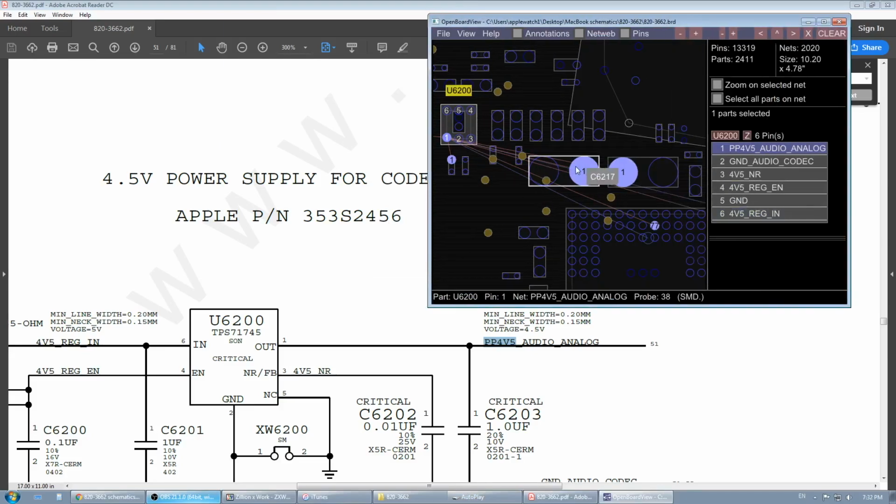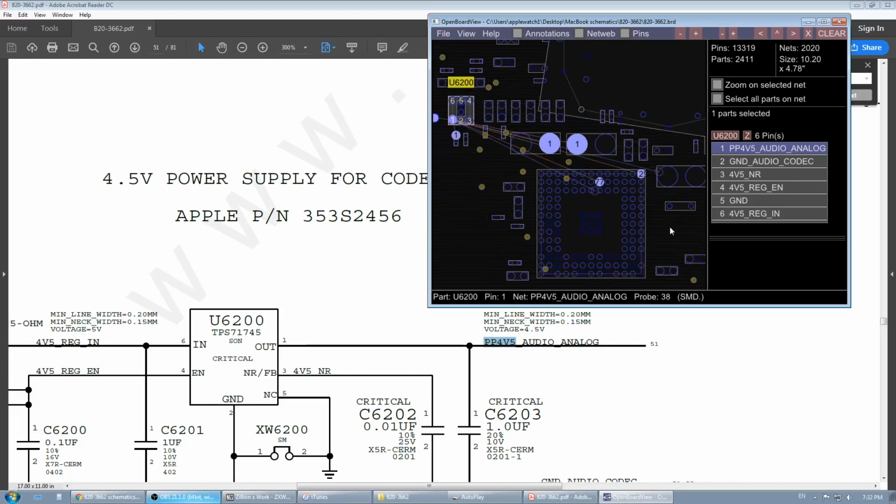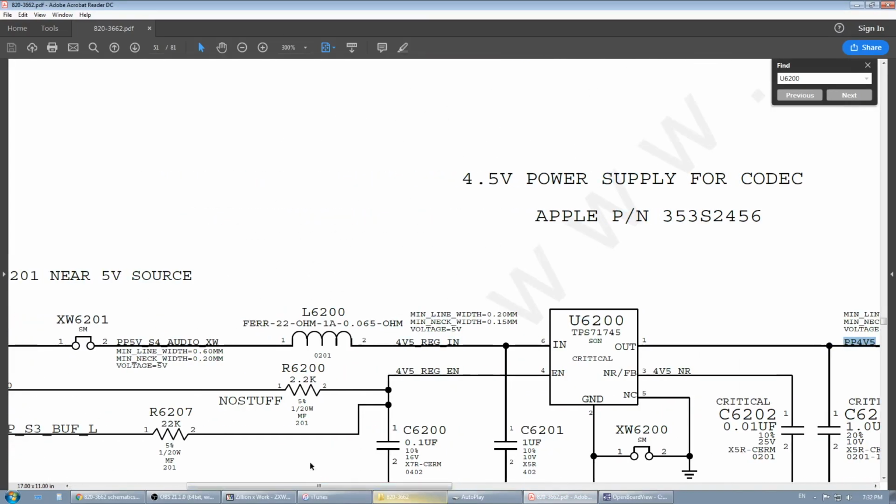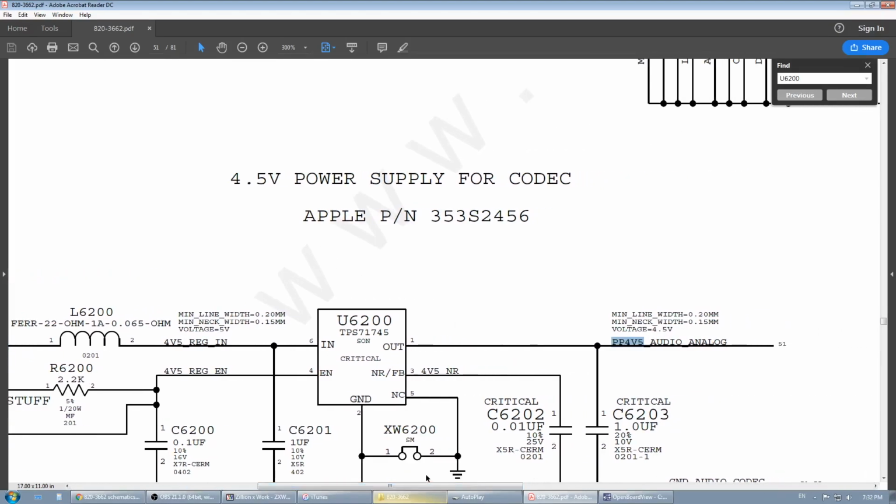I'm gonna input a voltage on this capacitor or this capacitor. Basically, I'm gonna input a voltage on this line to see where it's shorted. It's gonna heat up, and I'm gonna be able to see where it's shorted. I removed this chip, so this 4.5 volts is not gonna go backwards to this coil. So yeah, let's get started.